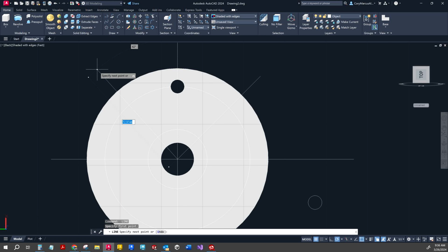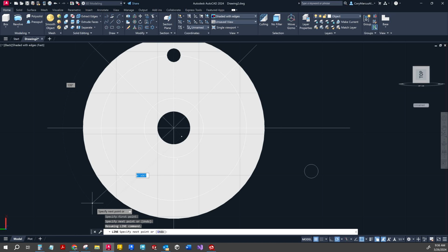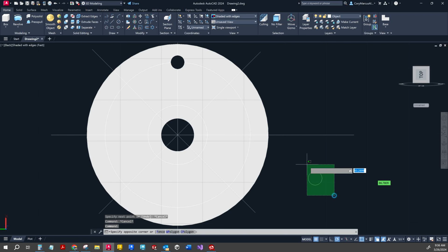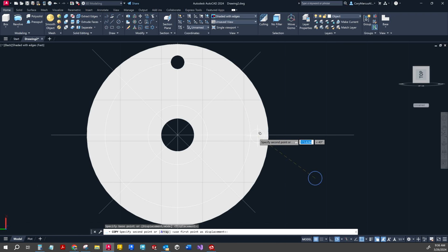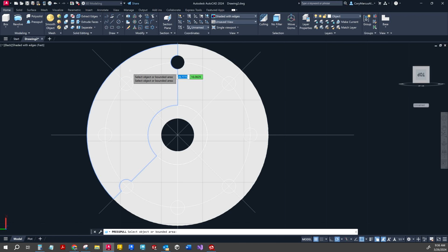Gonna do the same thing over here. Same thing over here. And there we go. So now at every crossing, we'll just snap on one of these. And so I'm going to do a copy. Grab the center point, and we'll just hit that quadrant, intersection, quadrant, intersection, quadrant, and intersection. And I don't think you can grab multiple profiles at once, but we'll see.